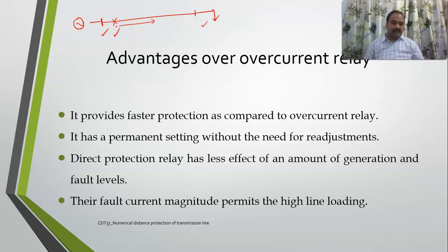Now you can ask me why we don't use an overcurrent relay, because if there is any short circuit, then automatically an overcurrent relay will be helping you out, right? Yes, this is a very good question. Why is the overcurrent relay not regularly employed? You can employ an overcurrent relay also, but the problem with the overcurrent relay we have seen in the last week. We need to choose characteristics, we need to choose operating TMS, we need to choose PSM, etc. And moreover, the overcurrent relay operates a little bit slower when compared to your distance protection.